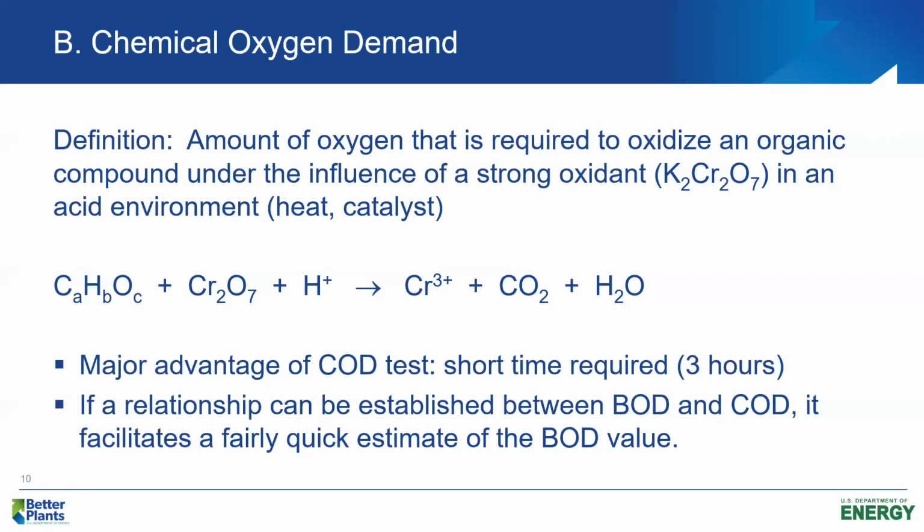So if you ask me, Larry, what approximately is the biodegradable portion of the organic matter in raw sewage? Well, what we do, we take the BOD ultimate, 300 milligrams per liter, divided by the COD, which is 450 milligrams per liter, and that's a ratio of 2/3. So what that tells us is about 2/3, typically, ballpark estimate, of the organic matter in municipal wastewater is biodegradable, and about 1/3 of the organic matter is not biodegradable. But again, the COD test, its value is primarily in the amount of time it takes.